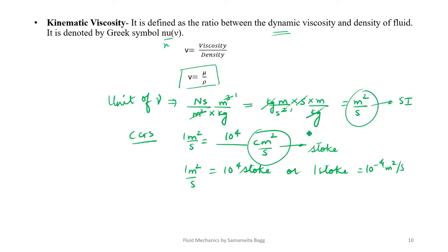The reason for discussing this term Stokes is that in the handbook or the data book, as you can call it, you will find the value of viscosity of oil in terms of poise and Stokes. That's a way of representing. Hence, we should know about these conversions. And one more conversion is 1 centi-Stokes is 1 upon 100 Stokes.